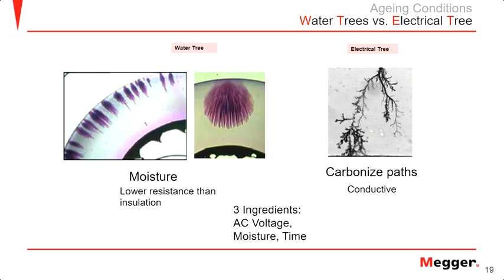Now, if we are looking at electrical trees, which typically grow from the conductor towards the insulation, pointing outwards, they can also develop in trapped space charges, or if you have voids in your insulation. They tend to grow electrical trees over time through partial discharge.